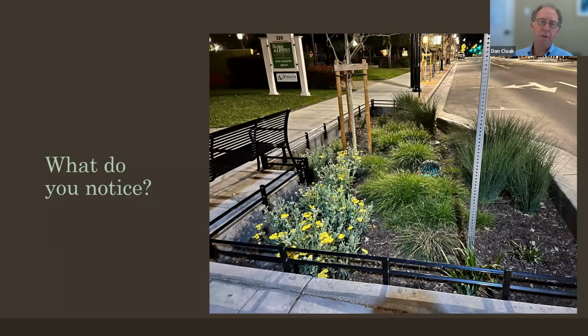That's the first answer to that question. And then if there's no way, because of the way the site's configured, that the landscape area can be prevented from draining towards the bioretention facility, the criteria in Chapter 4 instruct you to apply a runoff factor of 0.1, so 1/10, to that landscaped area. So you can have a lot of landscaping area going to your bioretention facility without having to greatly increase the size.